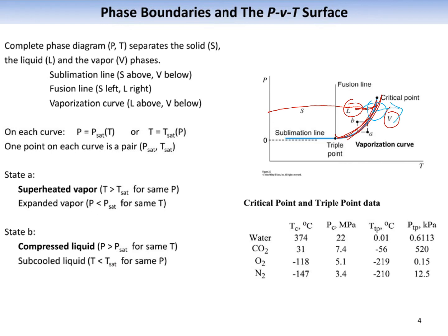Upon this line, the liquid and vapors coexist in the form of saturated vapors. If we further continue to increase temperature by putting in heat, the temperature will increase and now the vapor will cross this line and become superheated vapors. So all the vapors in this region are superheated vapors. Only saturated vapors are on this blue line.